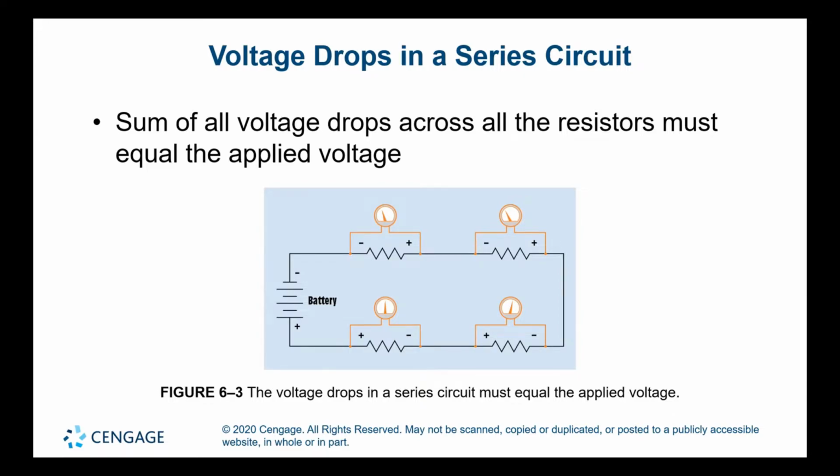Okay, so there is another way to say this as well, which is called Kirchhoff voltage law. Kirchhoff voltage law says that the algebraic sum of all the voltage around a closed loop will always be equal to 0, which means, in other words, that if we have, let's say, 20 volts here, and that's my input voltage, and let's say that all these resistors are equal, okay?